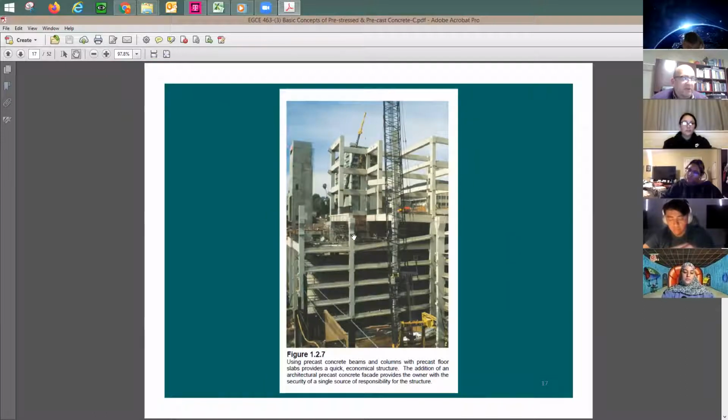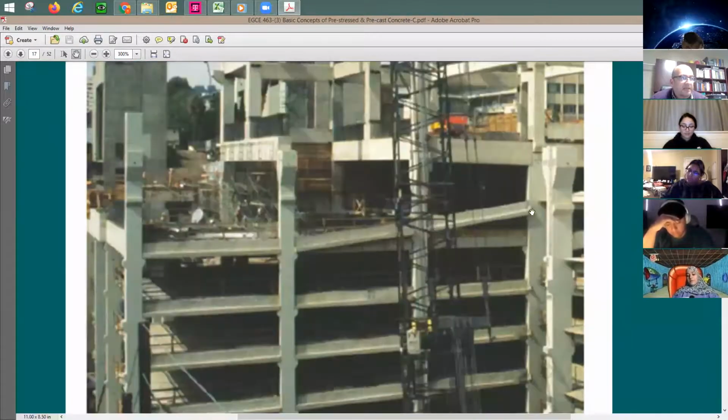One of the famous structures, this is here a parking structure, and it is made out of moment frames. So you have here some moment frames. And look, you can slope it. Look at the slope when you have a ramp. It is so easy when you slope it this way. If you just imagine that you build this out of conventional reinforced concrete, it's going to be a really tough job, especially when you have the ramps. Ramp is going to be a big issue for the formwork and the reinforcing bars. But in here, it's going to be much easier because the column comes with all the corbels at the exact height that you want. And also the beams come in the exact length. And of course, you're going to have some clearance right and left.